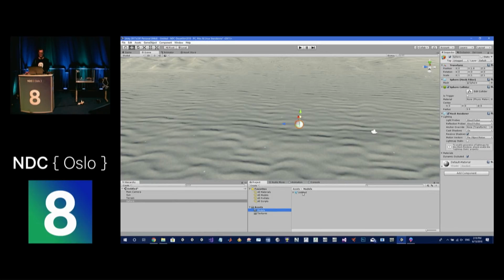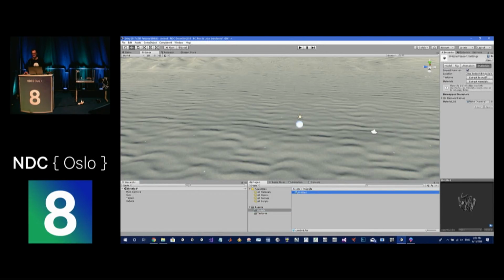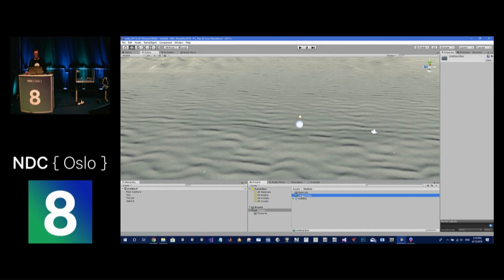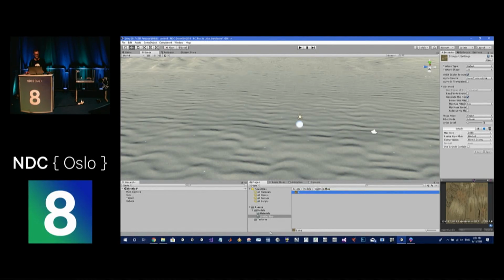Okay, so I'm going to go back into Unity. The model is automatically being detected. There are a lot of different things that you can do here when you're importing. But when I export from Paint 3D, I like to use the external materials. What this does, and I hit Apply, is that it takes the textures that got exported from Paint 3D and adds them in a separate folder. So I can see that it's currently in here. This is a very simple texture.